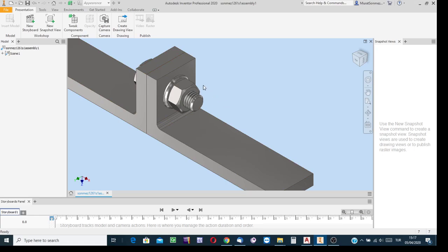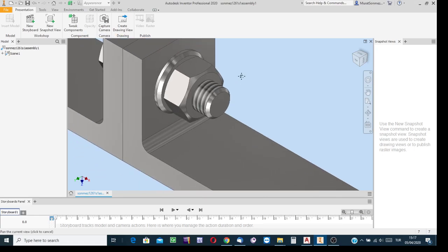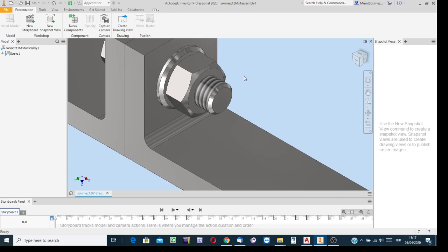So I am going to zoom in on this part to be able to clearly explain and demonstrate that the nut is to be unwound first. This is a right-handed nut. The helical groove within the hole of the nut is a right-handed groove. If it is a right-handed groove, then to unwind it, to unscrew it, it must be rotated in the counterclockwise direction. Okay.